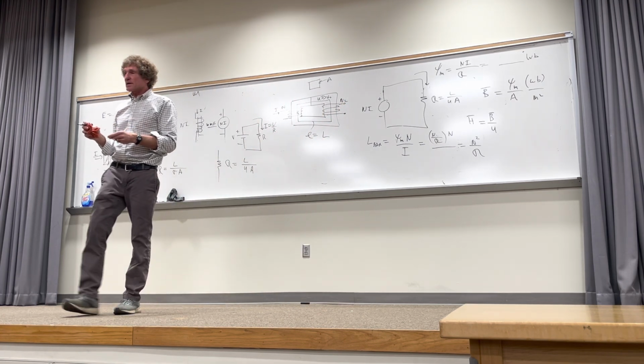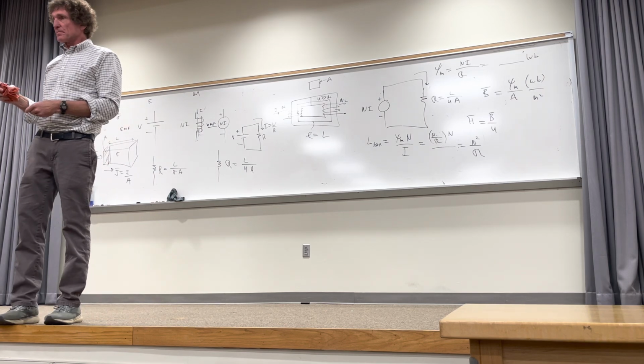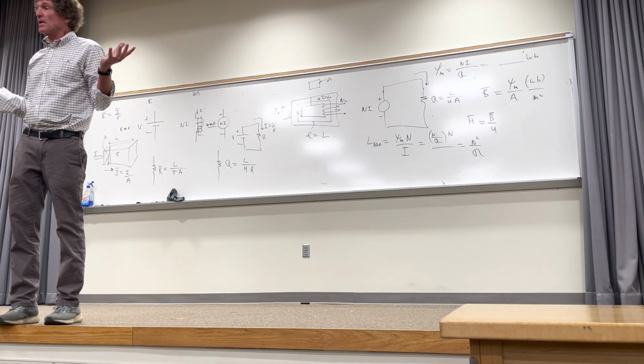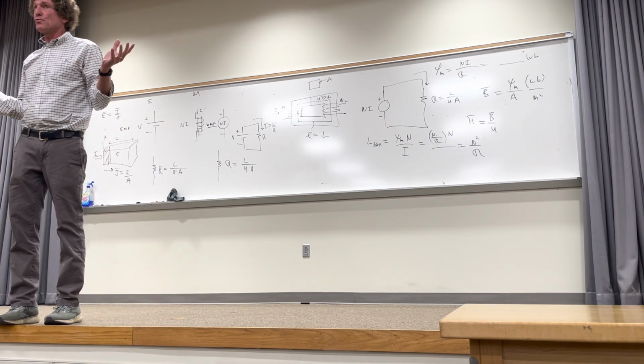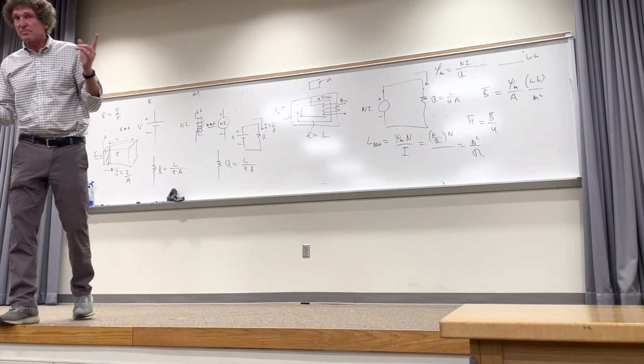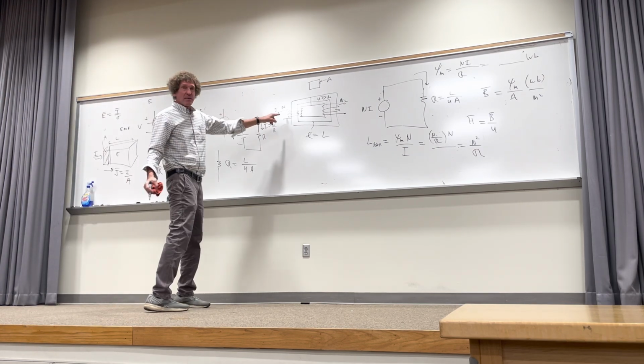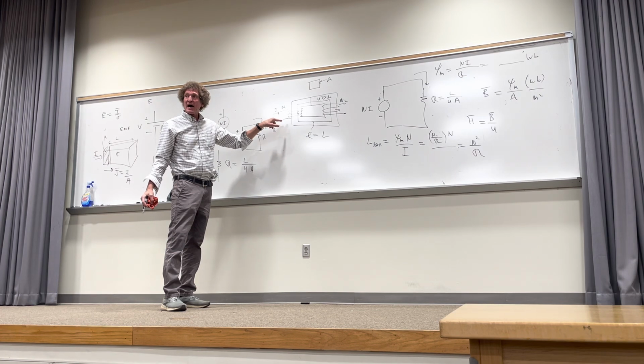Now, do I know the flux that's actually penetrating those cores? Yeah, I know the flux times N2 would be the amount, right? It's caused by what? The primary, right? So I divide by I1 of the primary, and now I have the mutual. Did y'all follow me on this one, class?